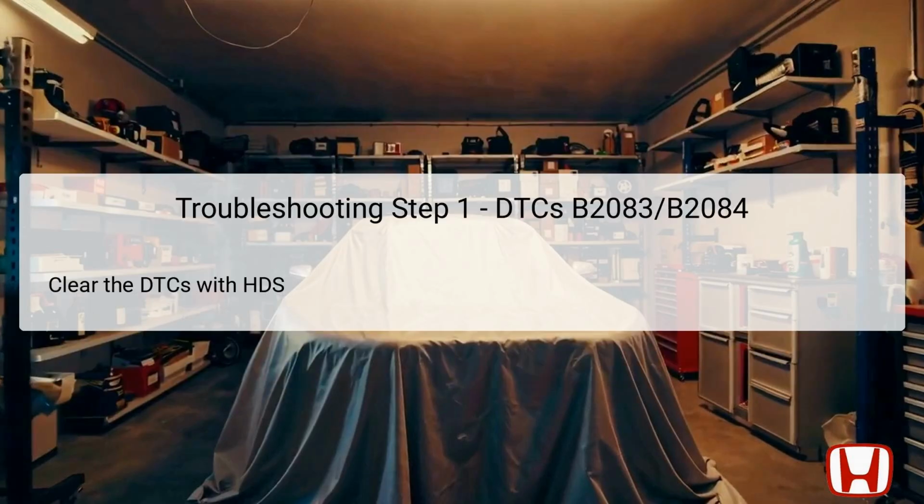failures. The first step in troubleshooting DTCs B2083 and B2084 involves using the HDS, or Honda Diagnostic System, to clear the existing DTCs. Clearing DTCs is significant since it resets the system and allows technicians to monitor if the codes reoccur after addressing potential issues. The HDS provides a detailed diagnostic report that helps identify specific faults within the vehicle systems.